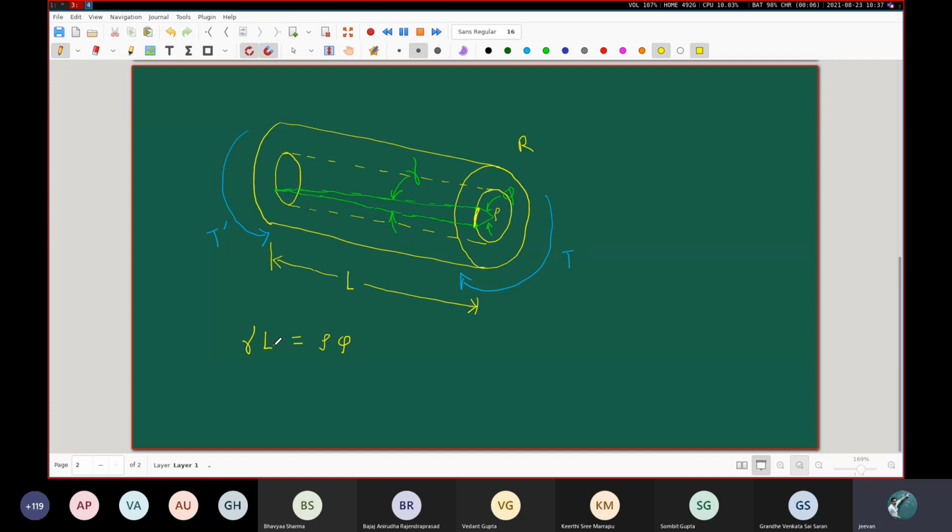All right. Sir, are gamma and phi very small angles here? Gamma and phi are very small angles. So the entire deformations that we are considering, I am drawing in a very big way only for the purpose of clarity, but you understand that the usual kind of materials that we use are metallic materials, or rather quite stiff materials. So the twisting that is actually induced in these shafts and beams is not like 25 degrees, 30 degrees, not like that, very small degrees.